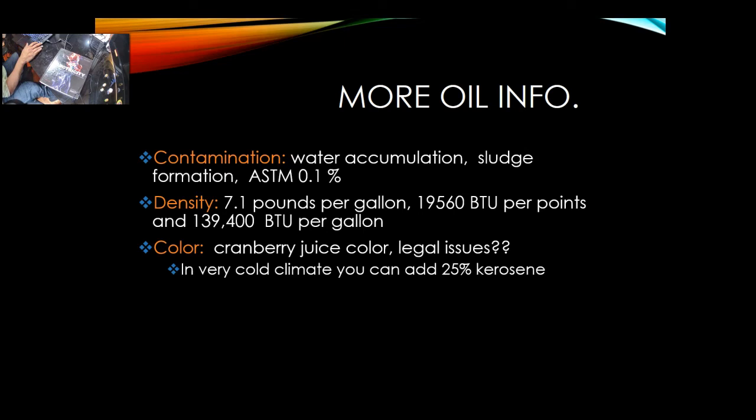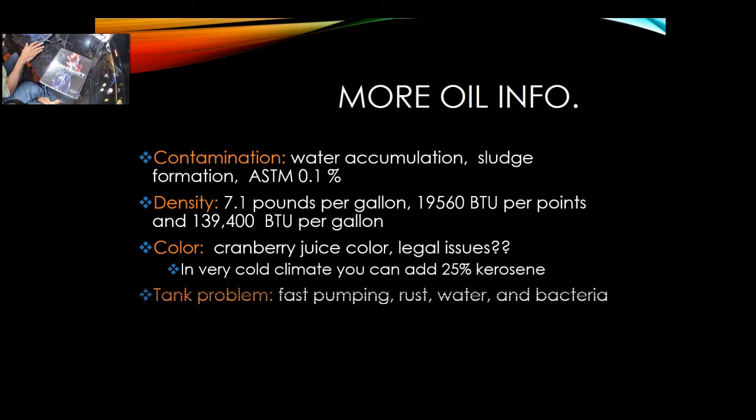You can add kerosene to make it more flowy. Do not add gasoline under any circumstances. That's a bad idea. Again, I've seen that happen. It's a bad idea. Tank problem. Fast pumping is an issue. Rust is a problem. Water is a problem. And also bacterial growth is a big issue for these kinds of products.